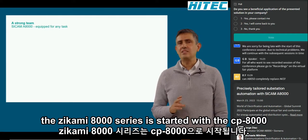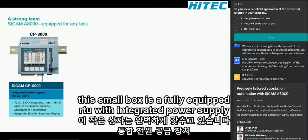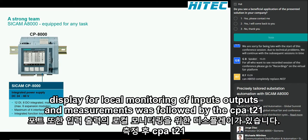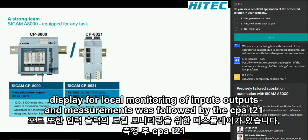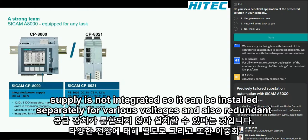The SICAM A8000 series started with the CP8000. This small box is a fully equipped RTU with integrated power supply, digital inputs and digital outputs. It has also 2 LAN ports and 2 serial ports. It also has a display for local monitoring of inputs, outputs, and measurements. It was followed by the CP8021. This has the same processor capabilities and ports as the CP8000. The difference is that the power supply is not integrated, so it can be installed separately for various voltages, and also redundant.